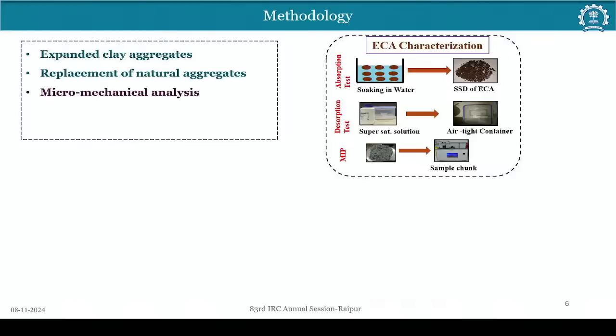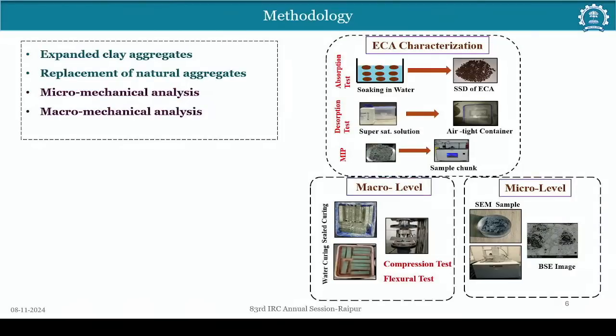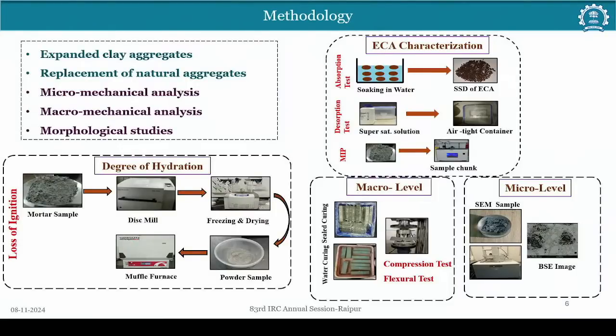Next, I have done micromechanical analysis, using BSE images, to analyze whether the water distributed across the lightweight aggregate is effective or not. Next, I have analyzed the engineering properties such as compressive and flexural strength using two different curing methods: one is water curing and one is sealed curing. Next, morphological studies such as the degree of hydration, how much hydration has happened due to this internal curing.